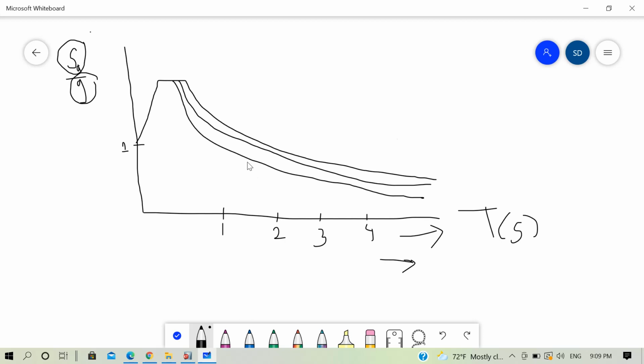So here, as we know that the mode shape of our building is associated with a particular or definite time period, we can plot values of different time periods on the x-axis in this fashion, corresponding to the different modes of vibration. First let's see here, we have three curves. These three curves represent the three different types of site classes. The lowest curve represents site class type 1, which is rocky or hard soil. The second curve represents type 2 or medium soil, and the third curve at the topmost represents type 3 or soft soil. So now we can draw a vertical line from these natural time periods, which correspond to different modes of vibration, to the corresponding curve.